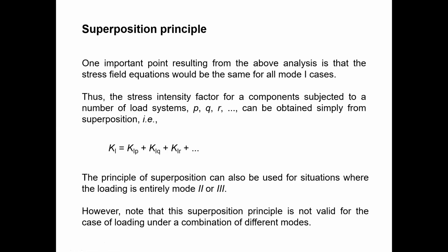Assume we have mode 2 and mode 1 together in one system; we can't apply the superposition principle across mode 1 and mode 2, because those are not independent. They are dependent. So we can't apply it for each mode separately and combined together. Only inside one mode can you apply the different loading conditions, find out the Ki values, and get the summation. If you only have mode 2, you can use the superposition principle and find out the total Ki.